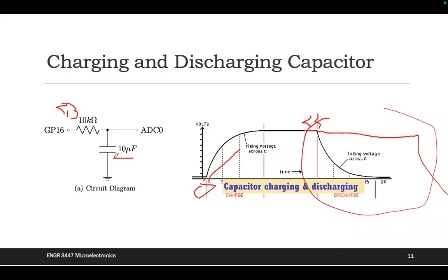For example, this is a resistor. This is, for example, 3 volts and 10 k, whatever. For this circuit, what is the voltage across the resistor? It will be 3, right? Yeah, it should be 3. And if you put another 10 k in parallel, what is the voltage for this one and this one? Same, right? It's still 3. That makes sense to you?